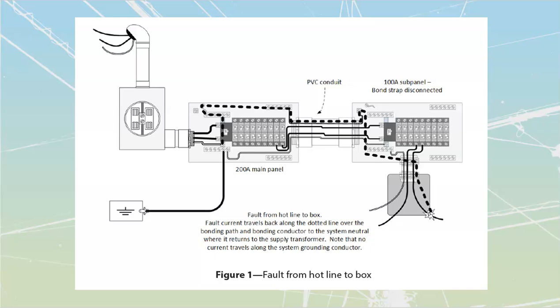What we have under a fault is the generation of what's called fault current. I know the term fault current sounds a little bit scary to us. We don't like the idea of fault current because it could be a big value, and it oftentimes will be. However, we do want to generate a large amount of current when we have a fault, so that we'll be able to actually activate the circuit breakers. Remember that circuit breakers and fuses are thermal or thermomagnetic devices. They need to have a bunch of current through them to produce heat or to produce overcurrents.